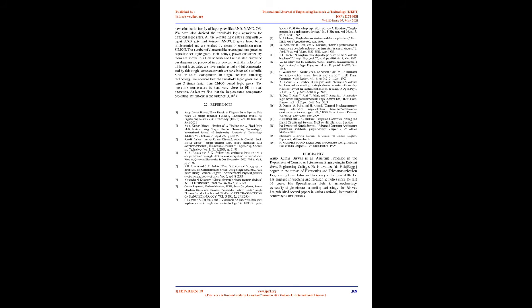Assuming that the error probability is 10 to the power minus 16, the delay for the 2-input OR gate will be 2.28 ns, and similarly the other delays for the other gates used in implementing the IC chip 74L85 can be calculated and are all shown in Table 12. It is transparent that the LTG-based circuit is faster than the SET-based circuit when the error probability equals 10 to the power minus 16. The comparison of delays for SET and LTG gate-based circuits is drawn by a bar diagram in Fig. 16.